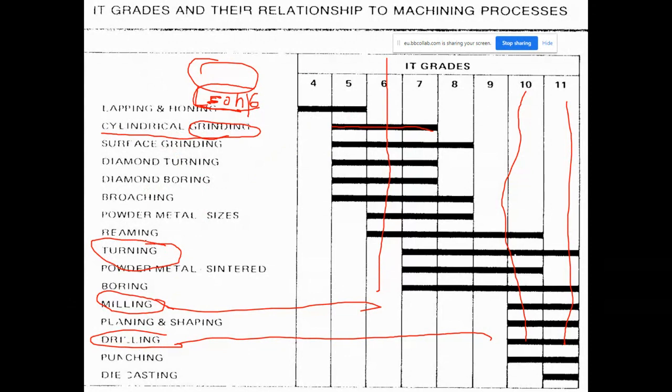If the surface is a flat surface, do not apply the turning process, but apply the milling process. Or the planing process. Planing and milling are the processes to cut material for creating a flat surface and setting its size.